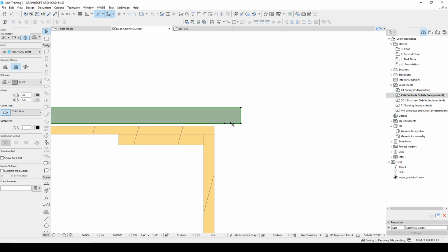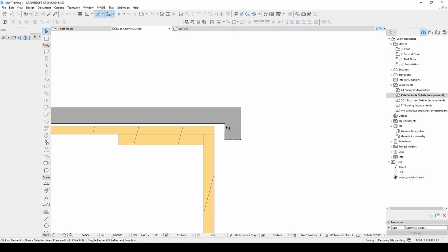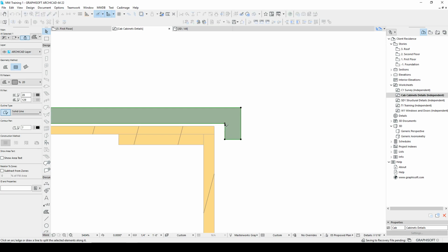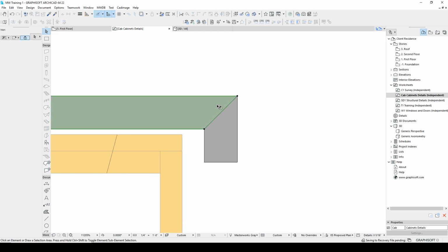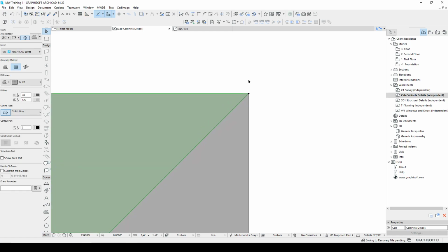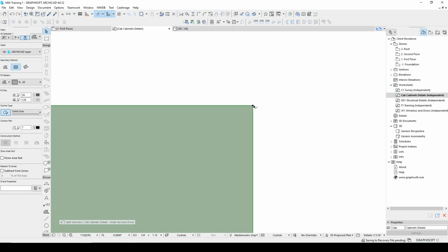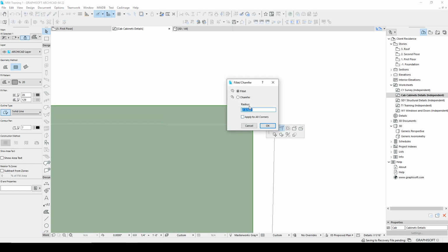And then we're going to be using a miter front edge, so I'm going to put a hot spot or a node there so I can pull this down, and I'm just going to bring it down another 3/4 inch, which gives me a 1.5 inch face, but you can do anything you want. Now here you have some choices. If this is enough information, then that's great. If you want to show the actual miter, you can put a line, cut these into 2 separate fills. If you want to show the beveled edge, maybe you put the beveled edge on here first. And this just becomes how much detail you want to put in.